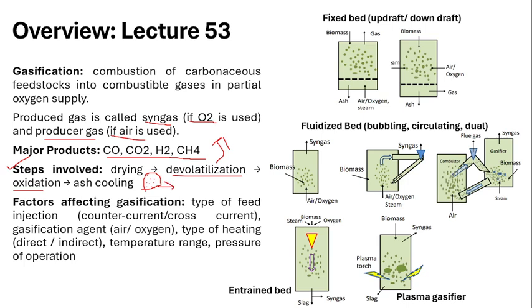Following that, what happens? Oxygen is passed into this solid particle, and the oxygen is going to penetrate in and out. Because of the oxygen, some substances are liberated as carbon dioxide, carbon monoxide, and so on. So oxidation will increase the pore size in the solid particle.